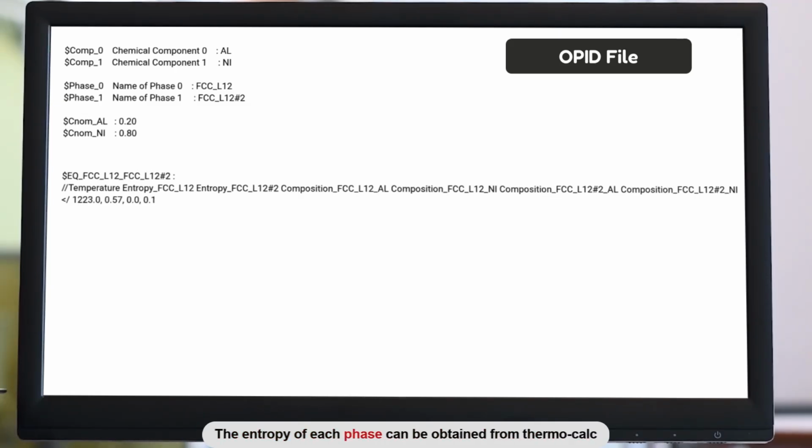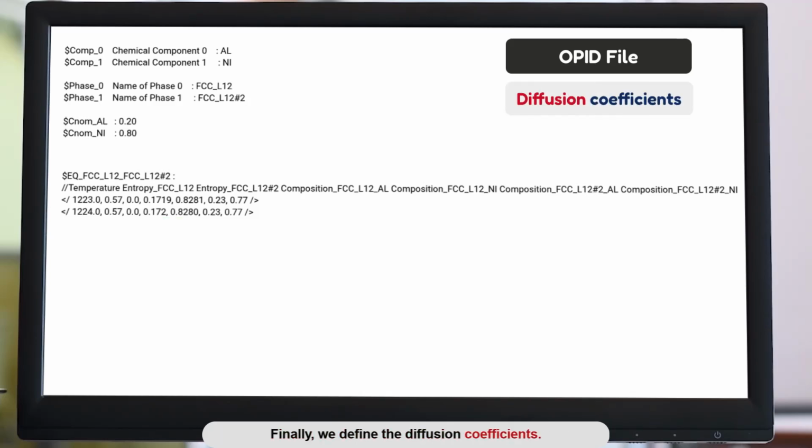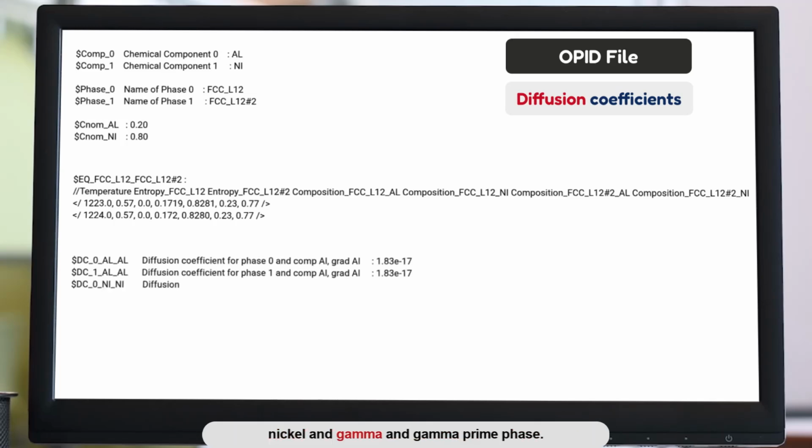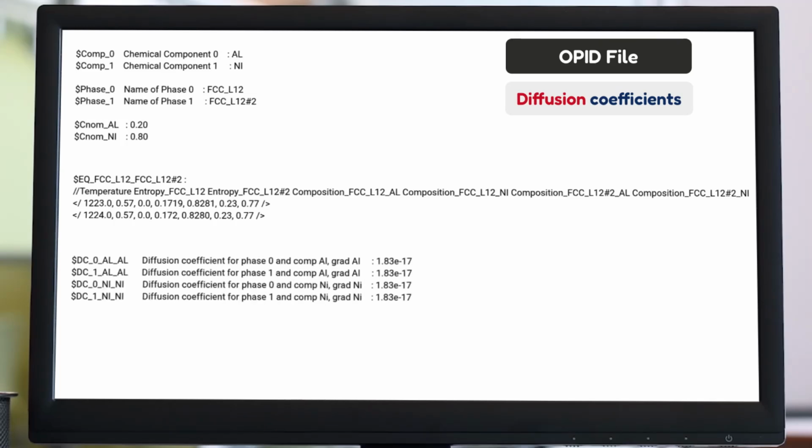The entropy of each phase can be obtained from Thermo-Calc or from literature data. The units of entropy are joules per mole Kelvin. The composition is given in mole fraction. Therefore, the sum of aluminum and nickel in the gamma phase must be equal to 1, and the same applies to the gamma prime phase. Finally, we define the diffusion coefficients. This includes aluminum in gamma prime, and nickel in gamma prime phase.